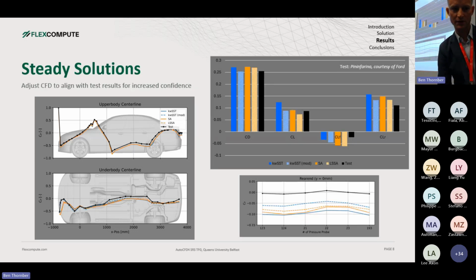And then stepping into where we understand a lot of industry practices apply different techniques to adjust turbulent parameters to help mimic or represent or align their simulations with experimental findings, whether in-house or otherwise. So this is something where we're intentionally modeling or modifying turbulence to help match up with the experiments to the greatest extent possible. We took a pretty one-off approach here, so we're not trying to get all those finite details out of the way, but we're modifying here in K omega SST, and we get a nice improvement on that leading edge area that I was just mentioning under the body.